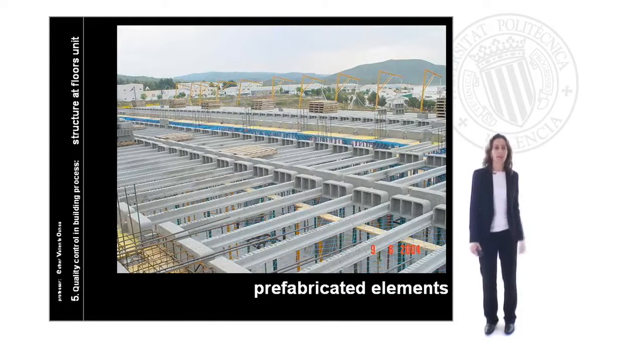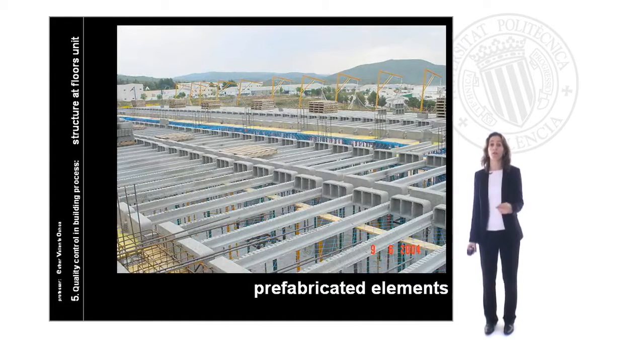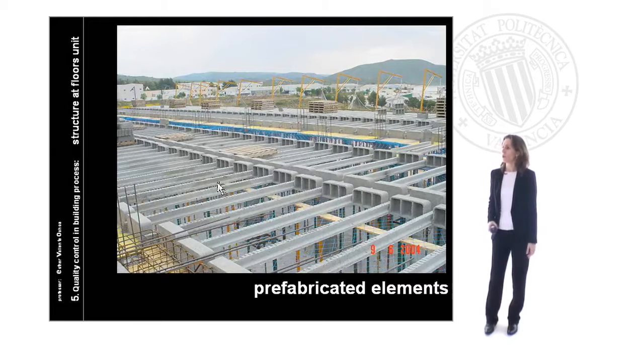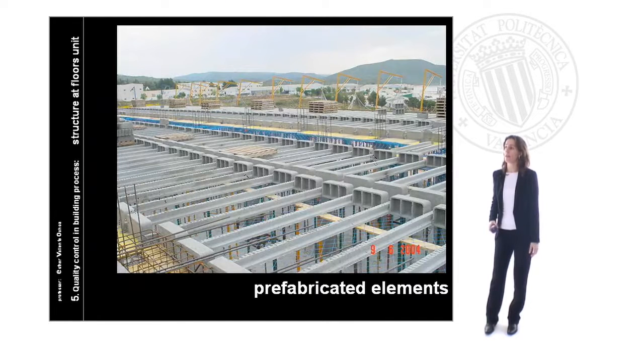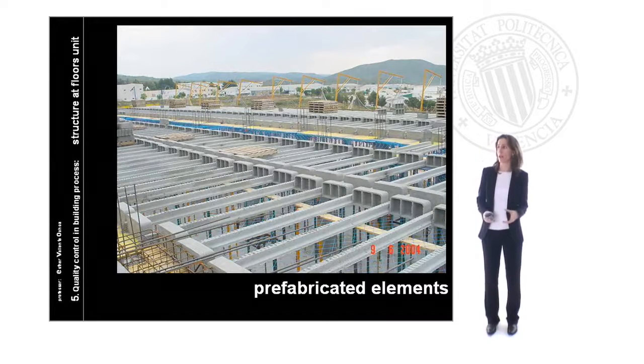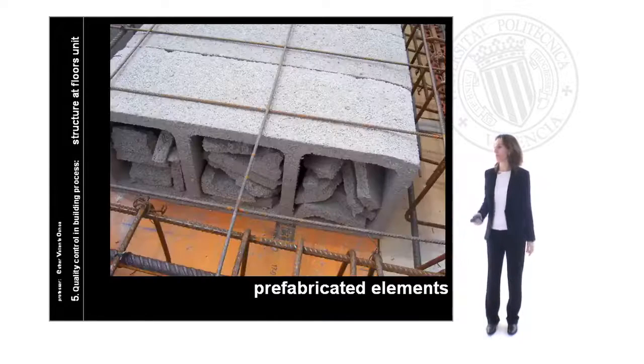Prefabricated elements are the first element you are going to put on in the floor. Prefabricated elements are divided into two types: resistant prefabricated elements and non-resistant prefabricated elements. They both have to be together at the same time because we are going to control the parallel between each of the prefabricated beams, putting on at the beginning and the end the little concrete floor tiles that will guarantee us the same position between the beginning and the end of the parallel beams.